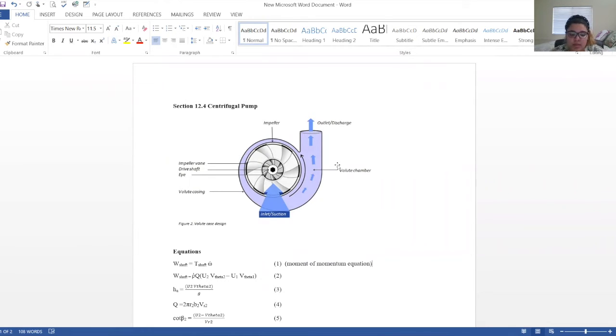Centrifugal pumps come in a variety of arrangements, but the basic operating principle remains the same all throughout. They are used to transport fluid by converting kinetic energy to hydrodynamic energy of the fluid flow. The flow through a pump is a complex process because of the unsteady flow and the three dimensions. However, the basic theory relates one-dimensional flow between the inlet and the outlet.